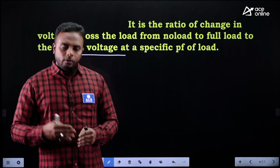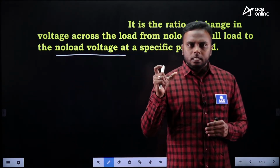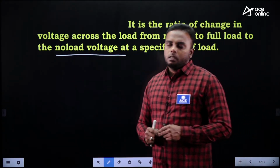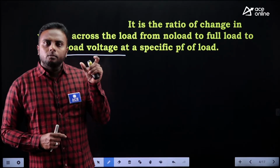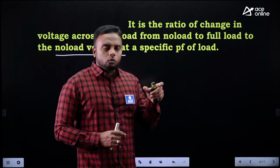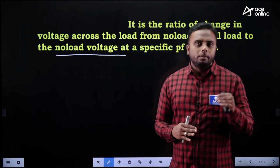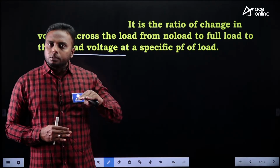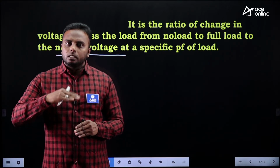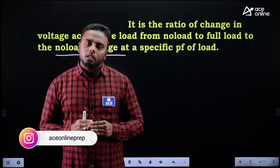In our homes also, whenever we check the stabilizers with digital readings, we can observe that the voltage is not steady always. Sometimes 230, sometimes 227, 228 or 222, 225. The voltages will fluctuate, depending on the load operation. Whenever loads are changing, the drops also will change. That's why those variations of voltage will be there. Approximately 4 to 5% will change in those voltages.